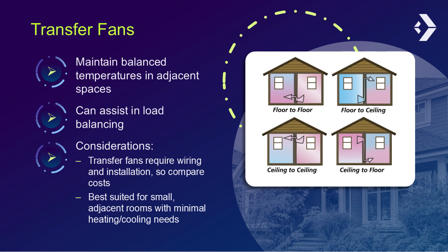This can result in fewer head units, less electrical work, and less refrigerant piping. These savings can accelerate the installation timeline and reduce both materials and labor costs. Of course, wiring and installing transfer fans isn't free either, so you need to look at the comparative cost for the specific situation to see if there are cost savings available.